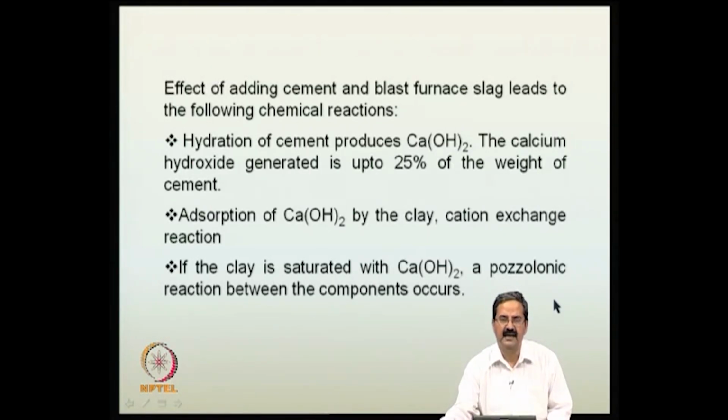What we see is that, for example, there is an optimum lime content in some cases, like you have an optimum moisture, an optimum lime content, and beyond that, strength decreases. So, you have an optimum content. In this case of lime, there is a continuous increase of strength, but we can't just go by that. We have to really see if you add say 5% or 6% or 10%, does it really give you the required engineering properties? That is what you are interested in.